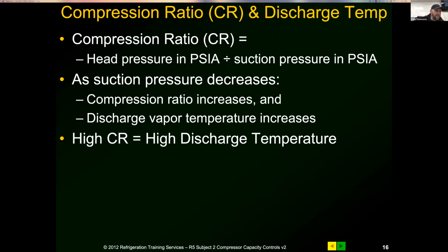The refrigerant only changes from absorption mode to rejection mode at the desuperheating stage, which is within the first couple passes of the condensing at the condenser. That's the first time it stops absorbing heat. So even though that discharge line is hot, it's still absorbing heat. If you have less vapor per stroke and it's still trying to absorb heat, you get too much heat per pound of vapor refrigerant flowing through that compressor, and you don't have adequate cooling properties. So you're not absorbing enough heat out of that compressor, therefore the heat keeps going up, and your pressures keep going up and up.